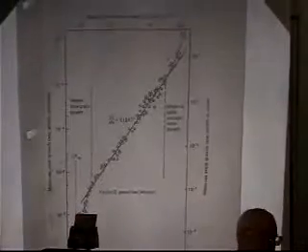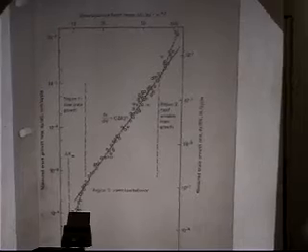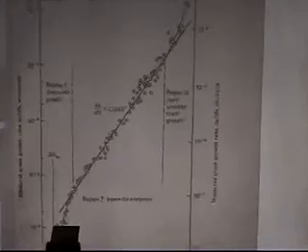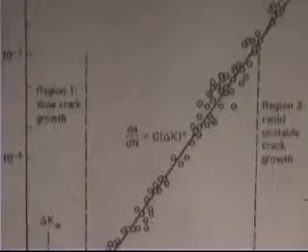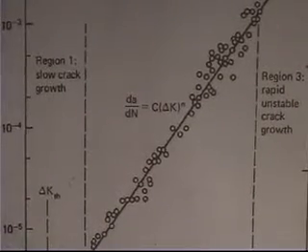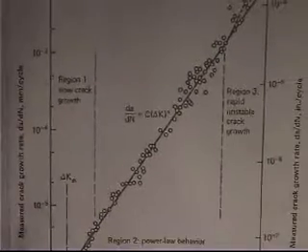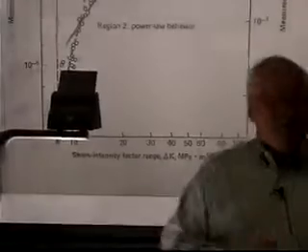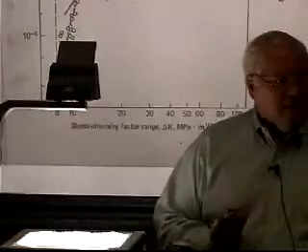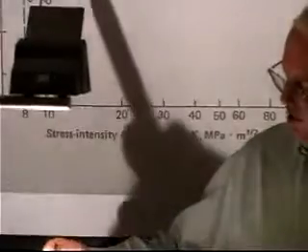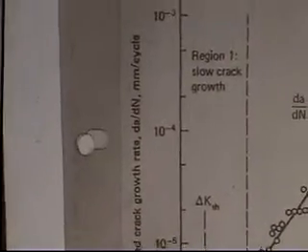And so this is one of the more complete materials. A533 steel is a pressure vessel steel used for nuclear reactors and things like that. Okay, so it's a fairly critical type of steel. There's lots of fatigue data on it. This is one of the most complete curves, and it shows kind of plastic behavior. So down here now on a log scale, everything becomes straight lines on log, right? Except it kind of goes through 3 stages. This is stage 1, stage 2, and stage 3. Region 1, region 2, region 3, typically called stage cracks.